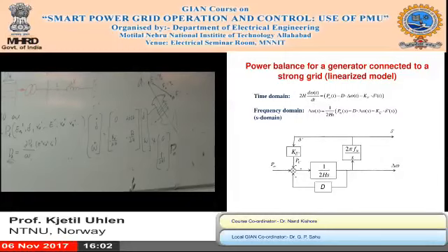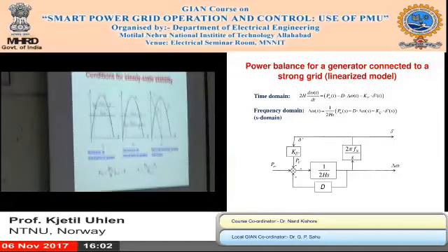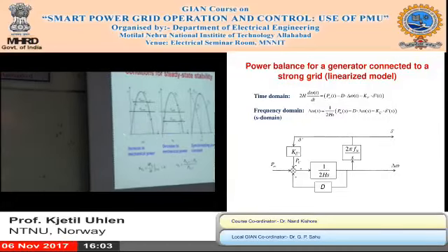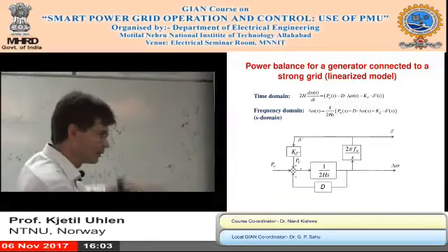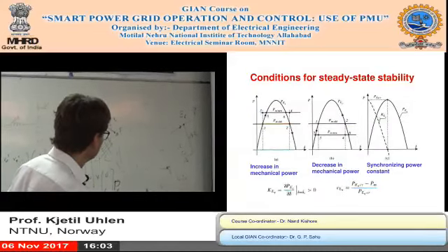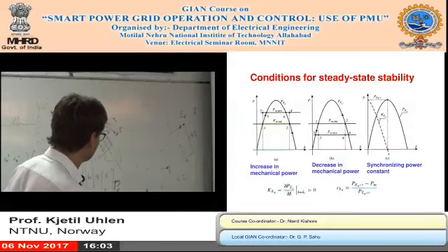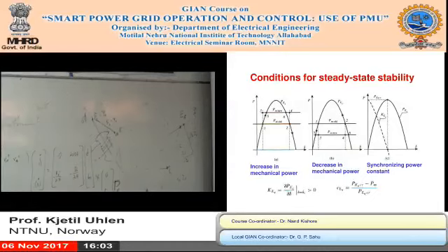And of course, what we need to take a look at is the validity of this now, taking into account that the power versus angle characteristic is basically sinusoidal form. We need to be sure, of course, that we are in a situation where we have a stable equilibrium. So basically, the synchronizing power coefficient, the K in my functions, has to be positive.